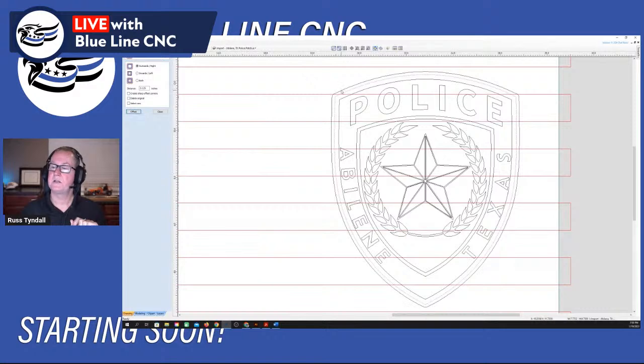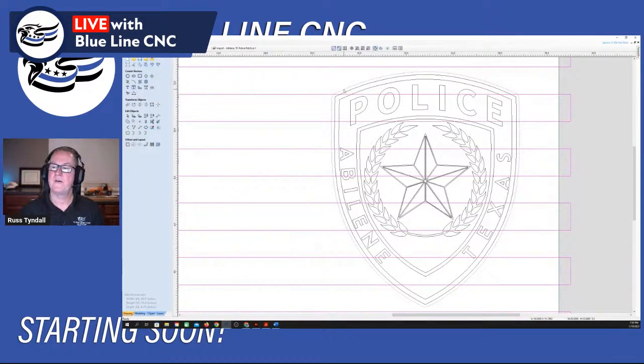You see what it did? It created an offset right here. So let's go ahead and select this offset. Excuse me, select our stripes first, and then we're going to use a trim function. Our stripes are selected, and then we're selecting that second, we're trimming to this offset that we just created. And there's our trim function. So we're going to select trim, and we're going to clear inside the boundary because we want everything inside this boundary gone. So let's hit clear.